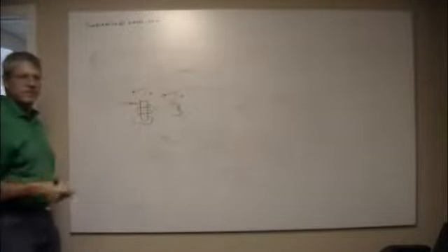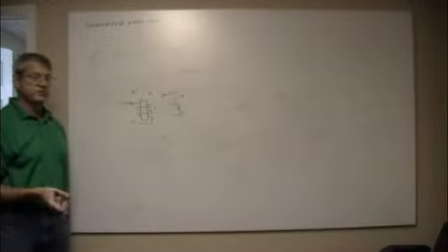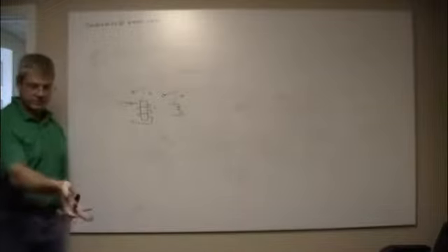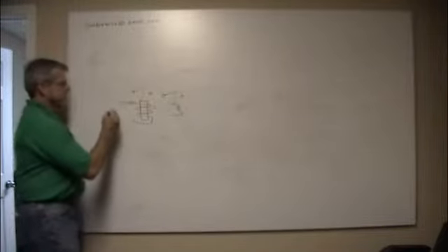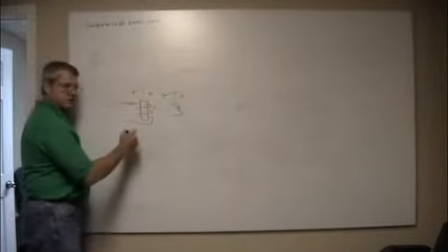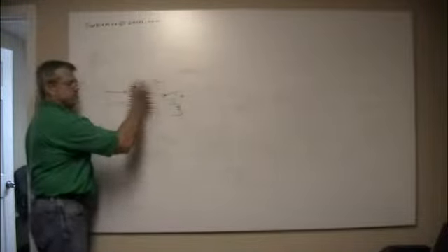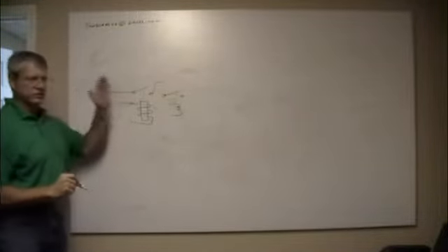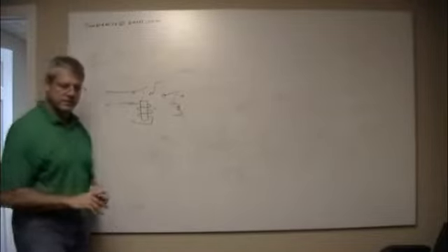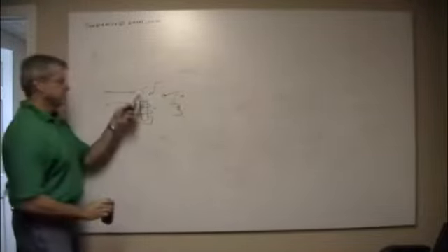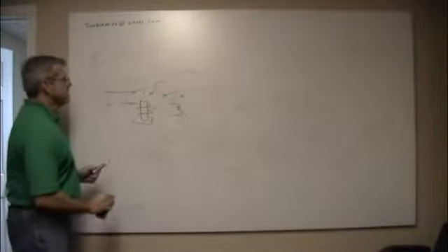That's a relay. That's really handy when you want to switch high currents, right? Your little microcontroller can give you 25 milliamps, but that 25 milliamps is enough to drive this coil, and maybe you've got a 10 amp circuit here, so you can control higher current, higher power loads that way. So that's why you would want to use this guy.